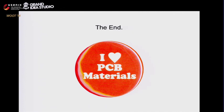But at that point, I'm not sure. The dangerousness of it outweighed the usefulness of it. If you have to do chemicals and that's your only way, then it's good. But if there are other options, I didn't really want to set up again to try that one. But I think there is one chemical, and it might be methyl ethyl ketone, that's designed for dissolving epoxies, that if you leave the board in there long enough, it will probably delayer.